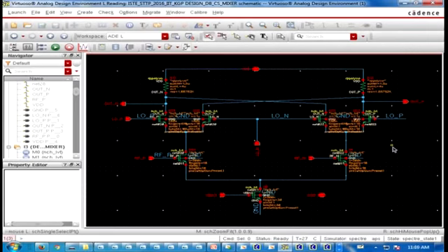When I started this mixer design, it took 3 days just to optimize these two resistances. If R is high, you will get higher gain, very good amplitude. But what is happening? The VGS is becoming less, so I am getting distortion in the output. My God, so how much time you need? Even 778 ohm, I remember in my first design, was my optimum resistance.